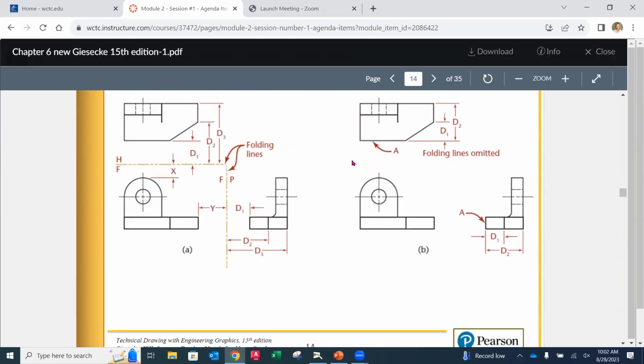in the olden days, we created everything manually, and you'll get a little experience with this. It's not like you're going to perfect this craft, but we had to put folding lines in. And then we measured from the folding lines how far back our features were. And that would set for us its placement in the view. Okay. So you'll notice we have a dimension or a D1 here. That's from the folding line back to where the front of the top view is going to be.